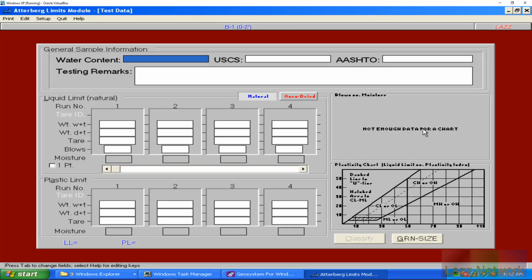So let me talk about Atterberg limits here, because you know it's not a fun last time unless he adds boring exposition to his everyday life. So Atterberg limits. The idea of this test is to determine your liquid limit and your plastic limit. A lot of these tests are named after people's last name. This guy's last name was Atterberg, and he helped develop this test to determine, like I said, liquid limit and plastic limit, so you can figure out your plastic index.